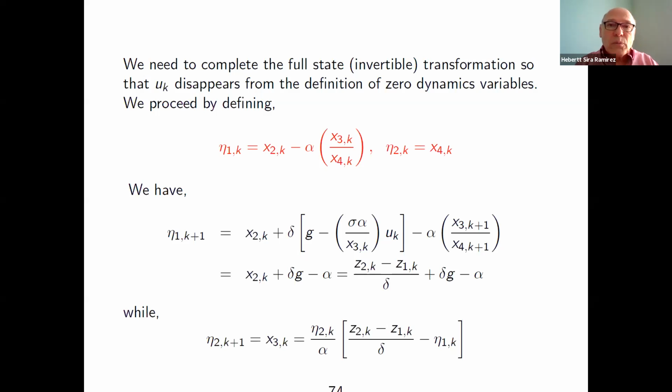And the boost example is one of the cases in which you cannot do the transformation because you need extra state variables. And that increases the order of the system. And the system is no longer state feedback linearizable because the entire dynamics has to be linear. And here you will be left with some zero dynamics again, even though it is not an inconvenient zero dynamics.